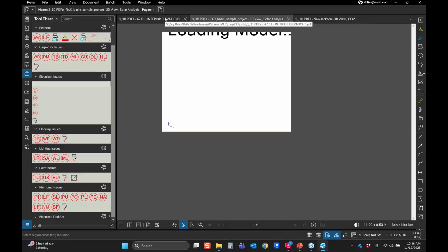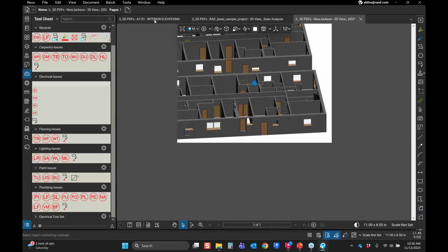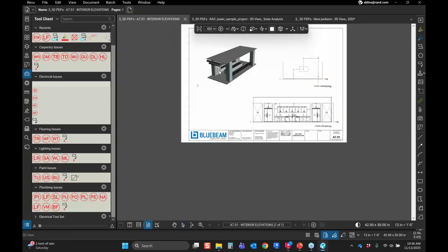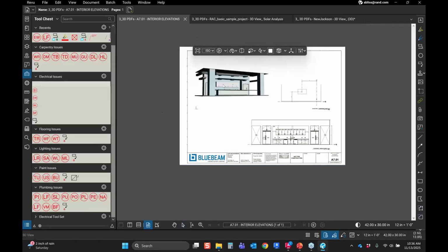I think, let's go to this one next. Yeah, so that's one way. You can just have the straight up model, like kind of on a PDF, like a print from that model space. This one, you can have the sheet view and we can do 3D viewports in it. So this is a 3D viewport of that kitchen. So you got the elevation right here.